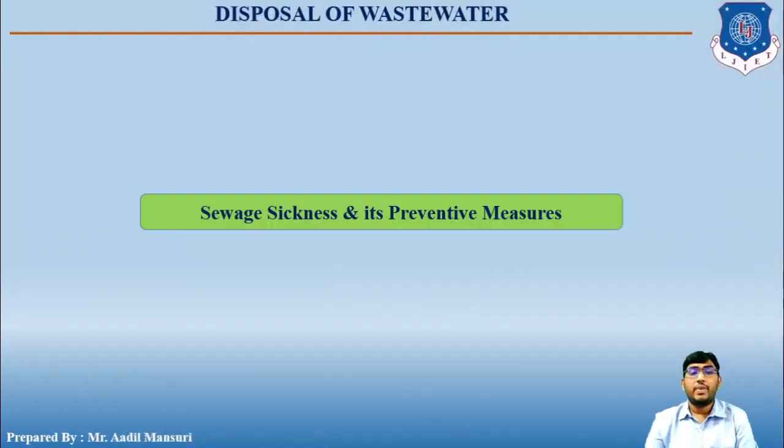So next topic is sewage sickness and its preventive measures. So when sewage is applied continuously on a piece of land, the soil pores or voids may get filled up or clogged up with sewage matter retained in them. The time taken for such clogging will depend upon the type of soil and the load present in the sewage. But once these voids get clogged, free circulation of air will be prevented and anaerobic condition will develop within the